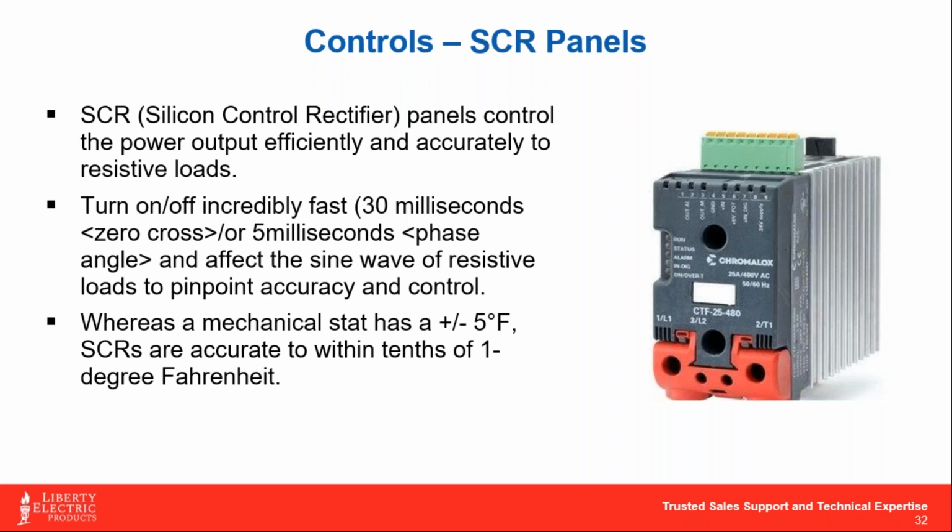What I like about this feature is that on startup, you're typically soft starting these heaters so that you're not getting that massive inrush current of, say, 480 volt or 600 volt directly onto a contactor that's being turned on and off like a light switch every 10-15 minutes.